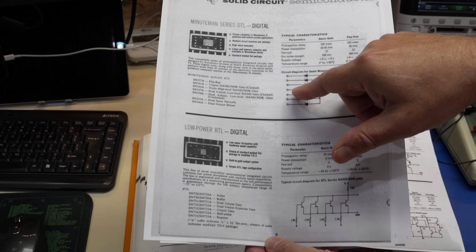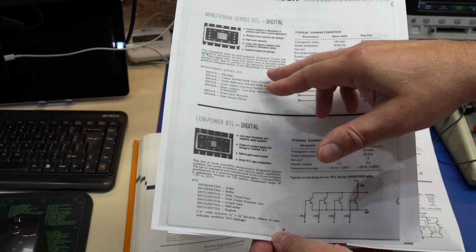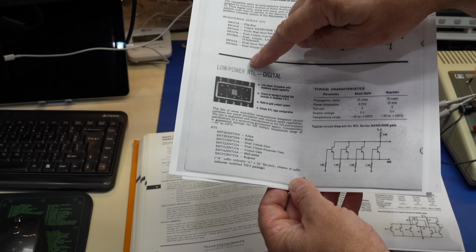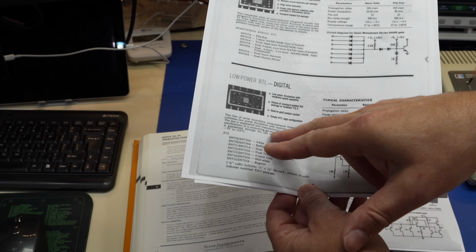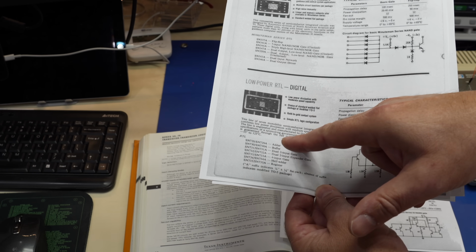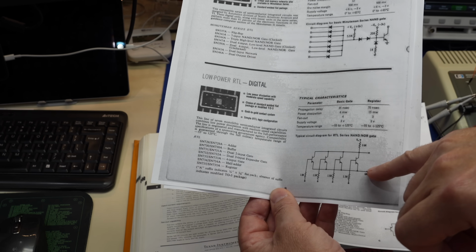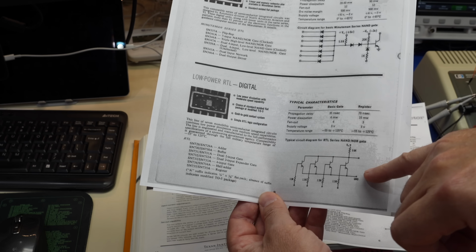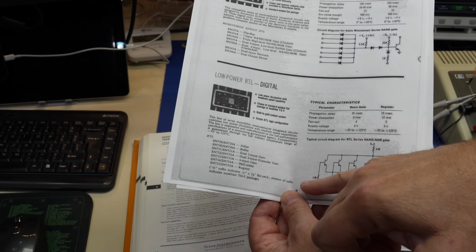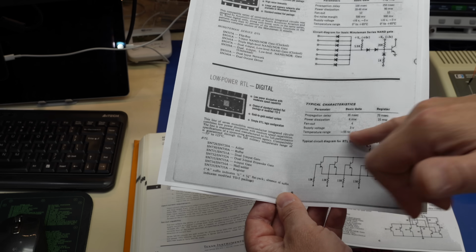This is similarly of military origins, made by North American Aviation for the Minuteman missile. And then here is another one, which is RTL, resistor transistor logic, manufactured to the full performance specification of a sponsoring government agency. Can you guess which government agency that is? So this is a gate I recognize. That's the one that was ordered for the Apollo guidance computer. It's a 4-input NOR gate. So eventually the 3-input was selected, but it's exactly the schematic.